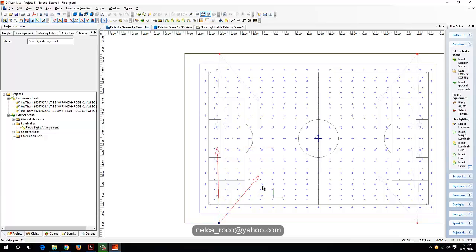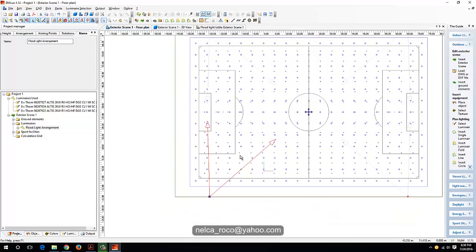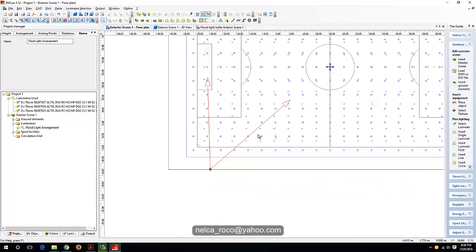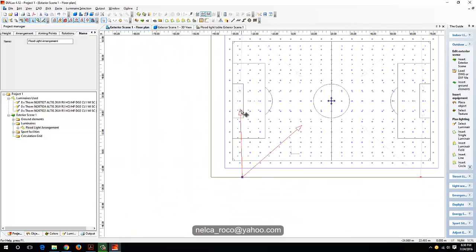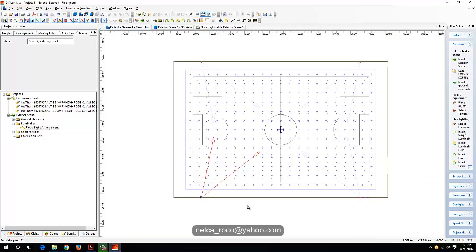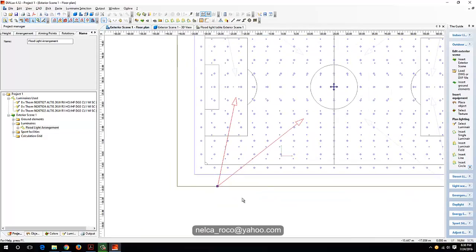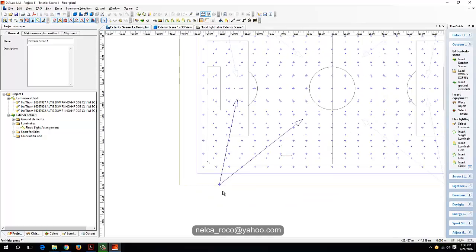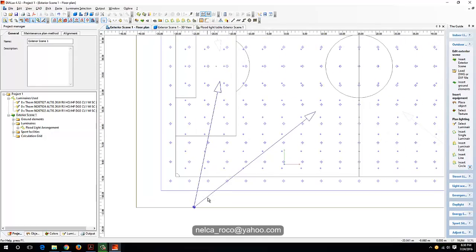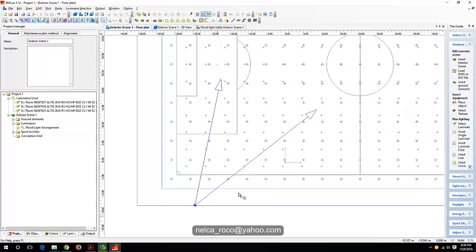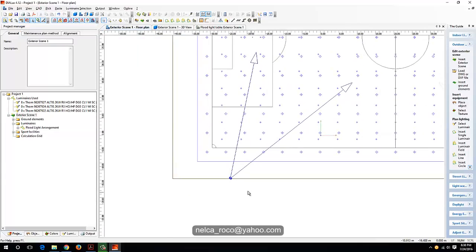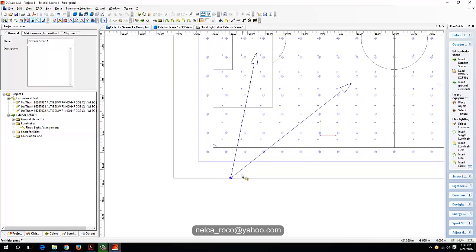You can measure that later, or we can offset or use a reference line to measure it. So, I aimed the floodlights now. And as per the rules, to reduce glare, in our practice the floodlights should not be aimed more than 70 degrees tilt, because otherwise it will be glary. We will check that later.